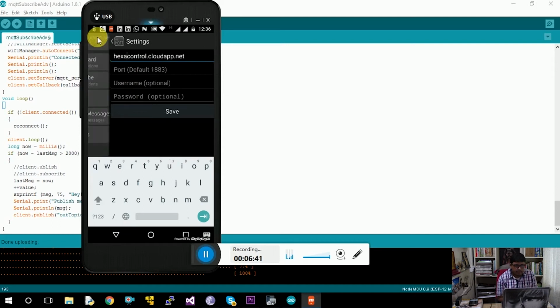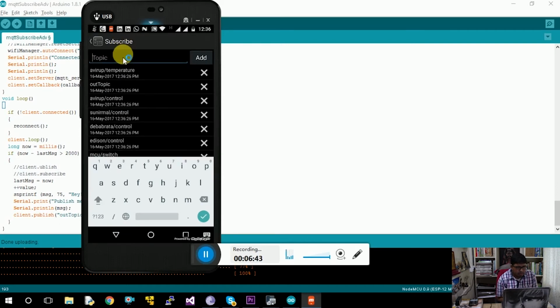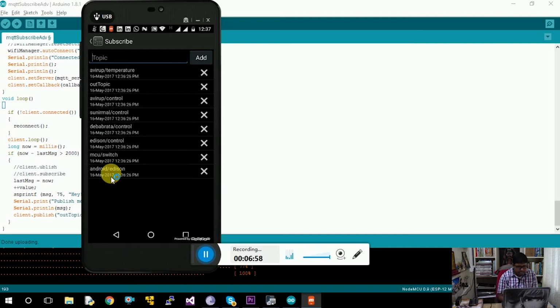Click on save. Now go to subscribe, add the topic you want to subscribe to and click on add. It will automatically be added over here, and I have subscribed to Edison/control and out topic. Android/Edison is there and out topic is there, because I'm using out topic to publish the messages, and out topic is used by the mobile to receive the messages, and Android/Edison is used by the MCU to receive the message from the mobile.